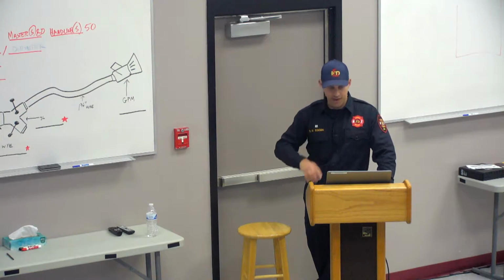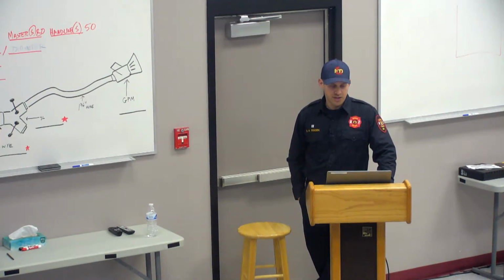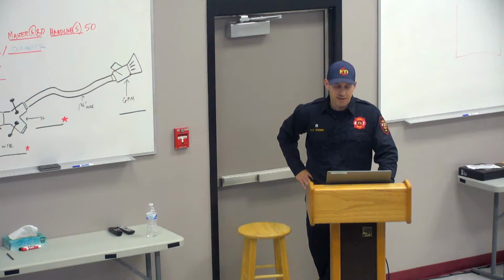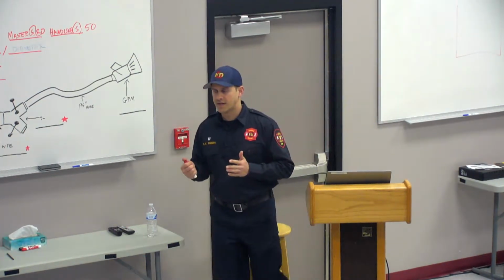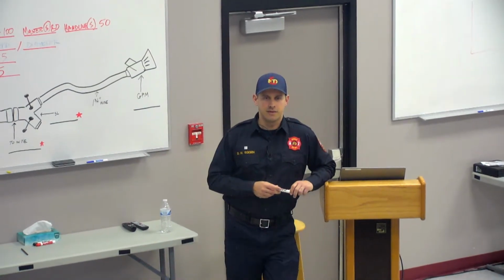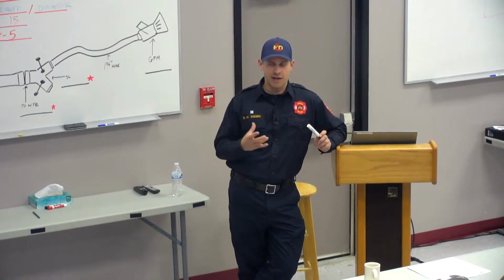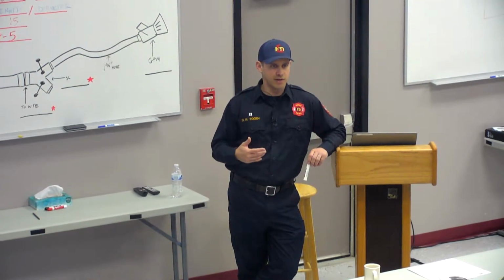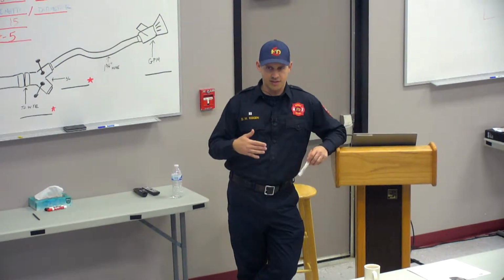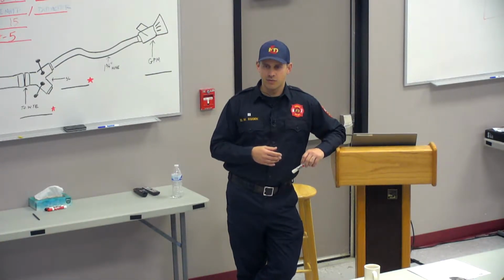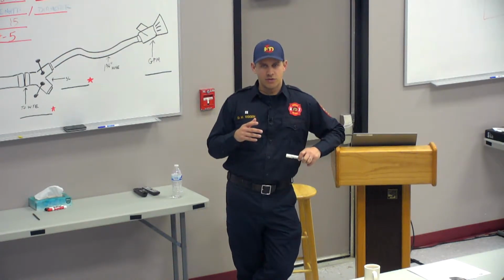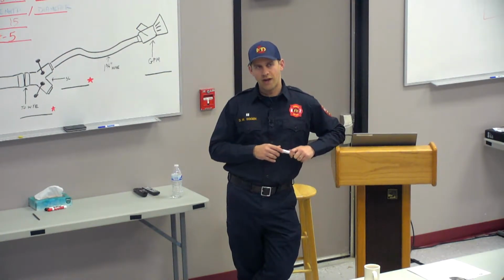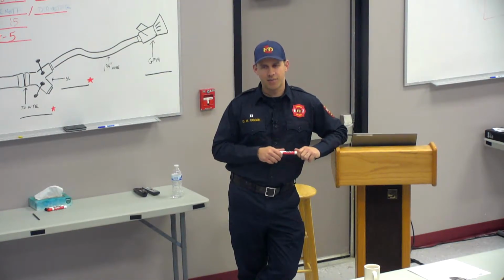Friction loss, we spoke about that. Friction loss is determined by the diameter of the hose and the length of the lay. Does everybody understand why that friction loss takes place? You have a hose line with a rubber jacket and water moving through it, right? Friction is created as it's moving against that, reducing the amount of pressure that is able to build up. So why do we not consider friction loss in standpipes or the piping that goes to our deck guns?